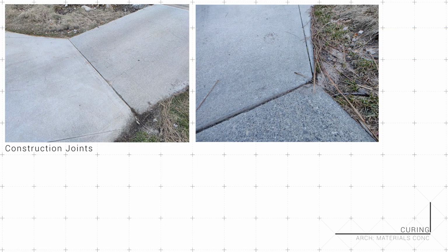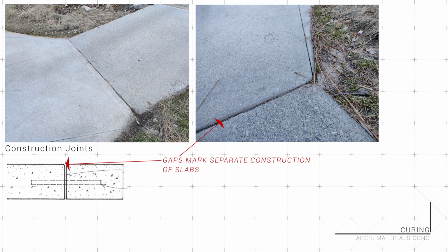With all this design that goes into joints, you'd think that we're at the end of it, but there's one left. Fortunately, it's much simpler. The construction joint is added purely for aesthetic reasons or for ease of construction. Nothing too special here. This joint marks where the formwork for one pour ends and another begins, basically open gaps that indicate separate concrete forms.